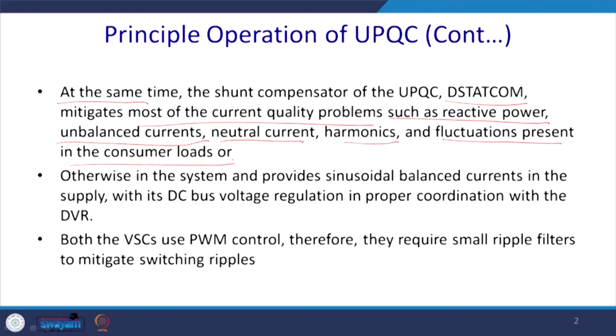Otherwise, the system will provide a sinusoidal balanced current in the supply with DC bus voltage regulation, in proper coordination with the DVR. This is the way that the UPQC should work, and both are voltage source converters that use PWM control. I shall discuss the grid connected voltage source converter control separately.